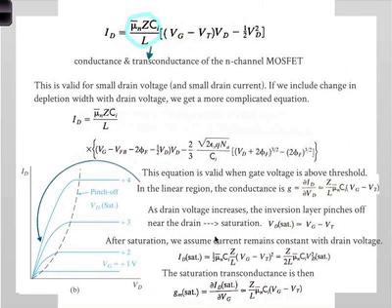So now we have what we are looking for. You can quantitatively describe how the MOSFET works in this case. So you have drain current related by some constant, which is shown in the blue circle. Forget that for the time being, and some voltage dependent term. You can see the dependence on the gate is linear. There's Vg. The dependence on the drain is quadratic. You have Vd and Vd squared.